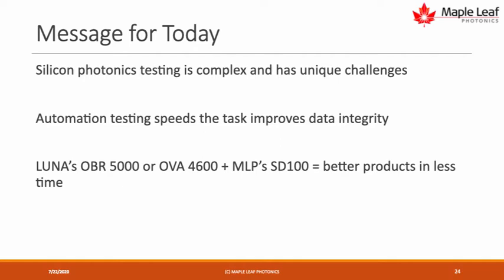And so what we'd like to point out is that you sometimes need to bring in high-frequency signals, you need to bring in DC bias, and a probe station lets you not only connect the optics, but also to set the configuration of the chip itself. And the earlier you can do that, the more insight and the more data you can get. And automating this, of course, is a big part of success because you need a lot of data to get a statistical understanding. There are variations from wafer to wafer or run to run. And you need this information to establish your yield profiles and focus your engineering resources to address the issues that pop up.